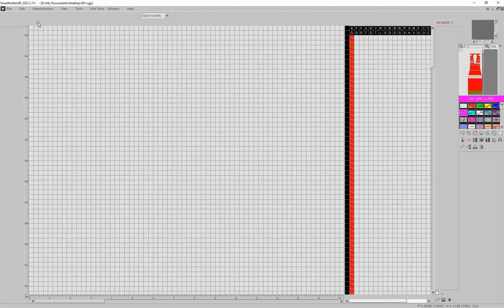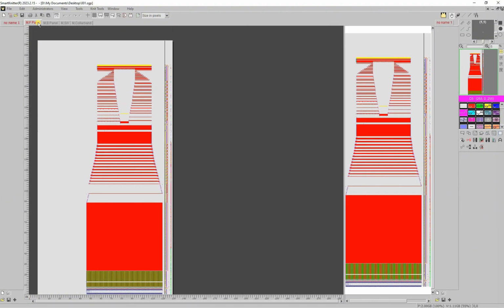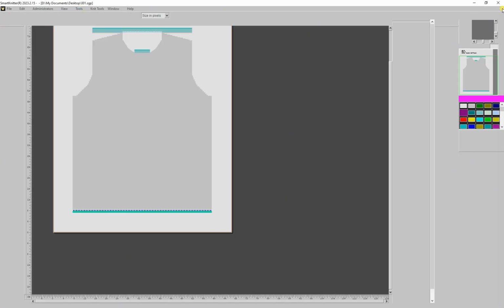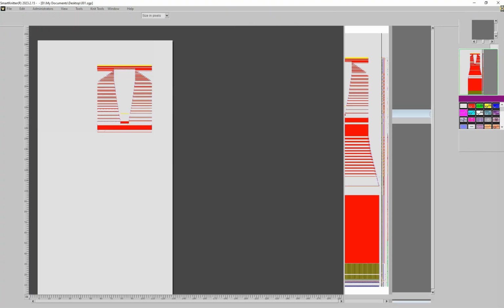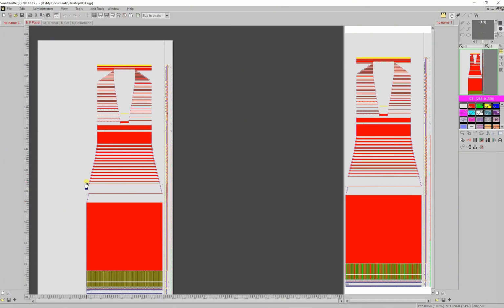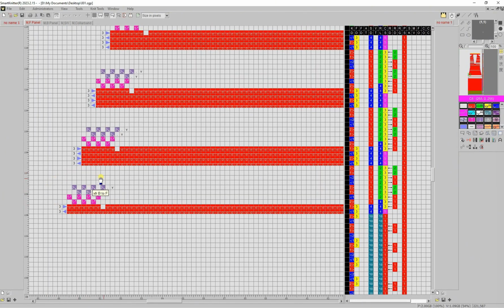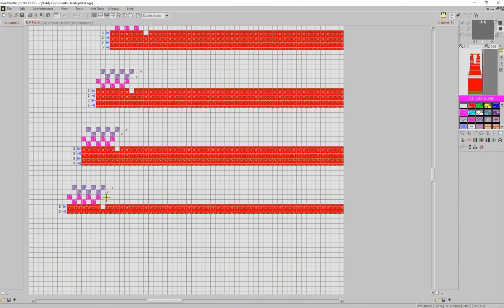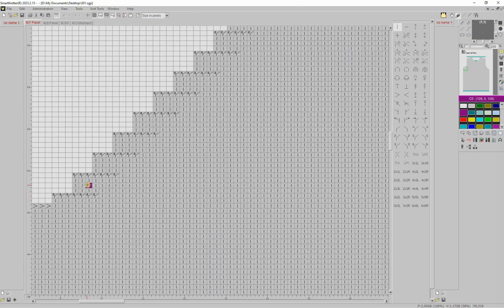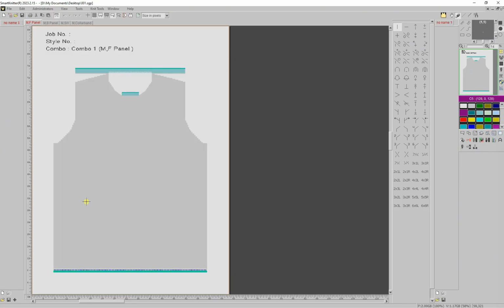Knit instructions and machine codes are saved in the same .sgp file, SmartGraph project. We can switch between them through this button. We can also navigate between these two using hotkey F12. Use F9 to zoom out and F10 to zoom in. Place mouse on the position where you want to inspect and press F12. This will bring you to the same position on its knitting instructions.